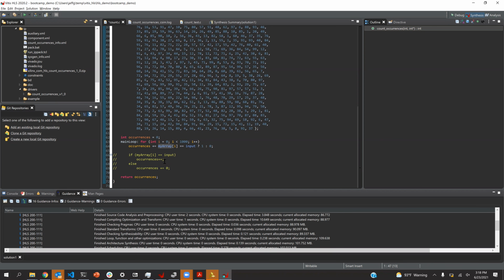Yeah, so it'll be much faster, but even if it wasn't that much faster, if you really cared about it, your processor could do other things while this is going on, remember? You could start it off, go do something else, and then come back and check the done signal. That's what's nice about these complex heterogeneous systems: we can naturally be doing two things at once, just by the fact that we're running software and hardware. So that gives us opportunity to speed things up that way.